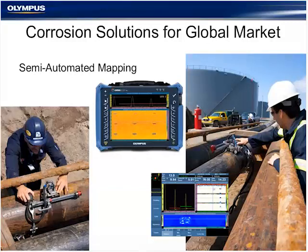And it allows you to essentially draw what you see on the screen there, which is called a C-scan. And this draws a map of your part, a swath of area that you wanted to cover. And so if you have an isolated area where you're concerned that the corrosion might be very much different from one point to the next, 3 inches over, this allows you to be very, very thorough with the mapping of that particular area and get a full 100% coverage of that.